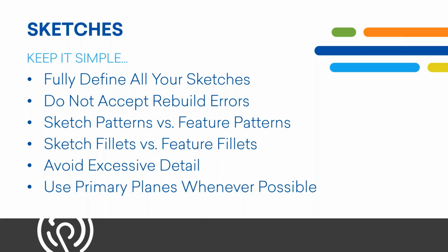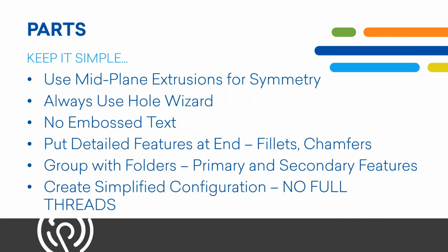So those make your models better, which will in turn make your assemblies better. So for parts, taking those sketches, creating the 3D features, you might want to try and think in terms of symmetry. If your model has the information on one side and then it can mimic or mirror it onto the other side, you're going to have a reduction in terms of your processing power.